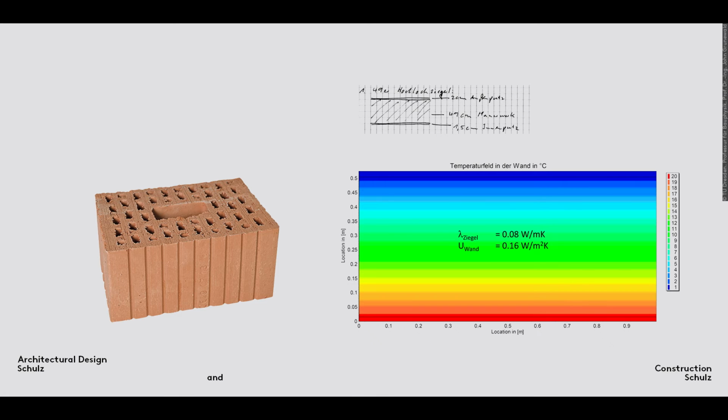Imagine a 49 cm thick, monolithic overground exterior wall made up of vertically perforated blocks. The heat transmittance coefficient, or U value, of the blocks is so good that no further layers, such as insulation, are required. This type of structure is known as a single skin wall or facade. For functional and aesthetic reasons, the masonry wall is finished with a strong uniform layer of mortar 1 to 2 cm thick, referred to as plaster on the inside and render on the outside of the building.